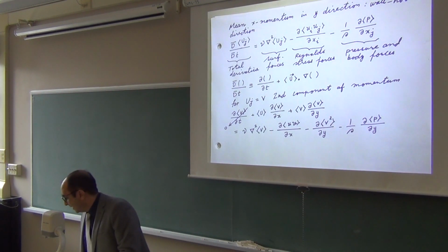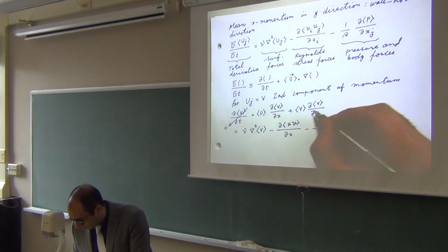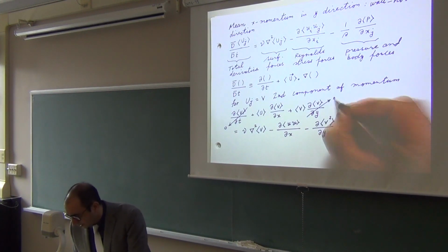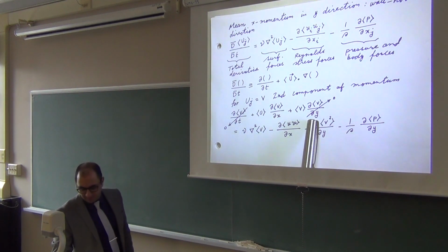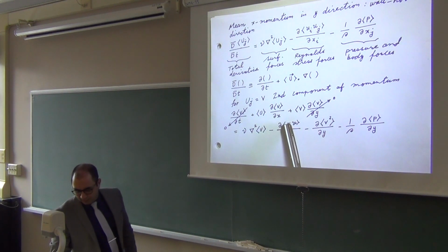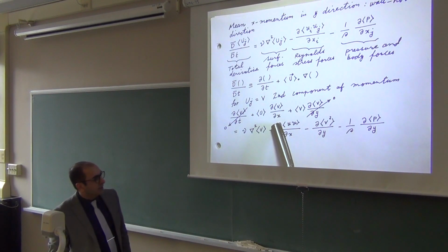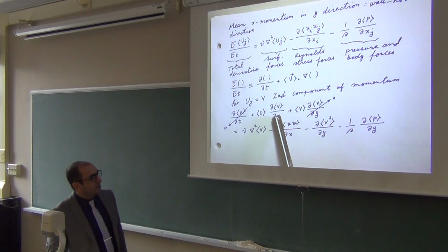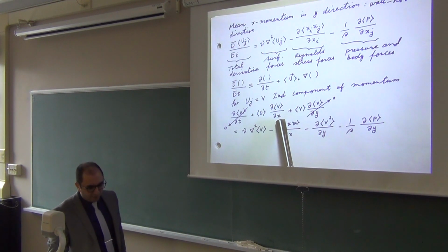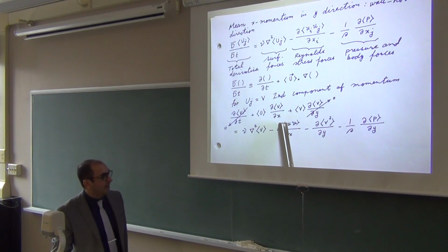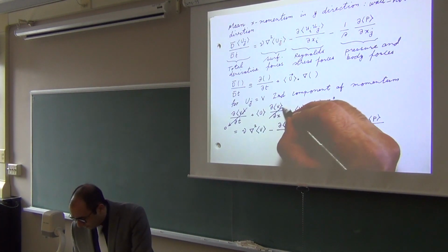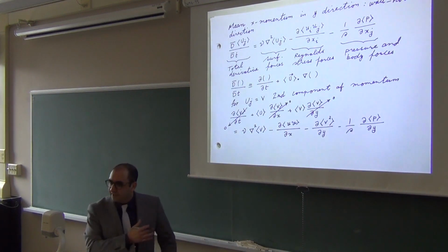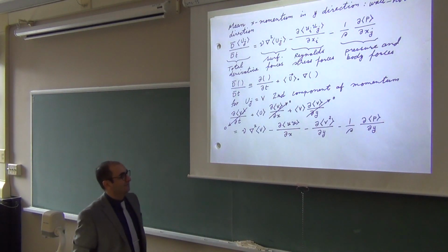I also found that partial v partial y was also 0. I just showed it to you on the last page. That came from the continuity requirement. Also, I told you already that none of the statistics will change in the fully developed flow in the direction of the flow, and x is the direction of the flow. So there's no change in mean vertical velocity there either. So all of the left-hand side is 0.